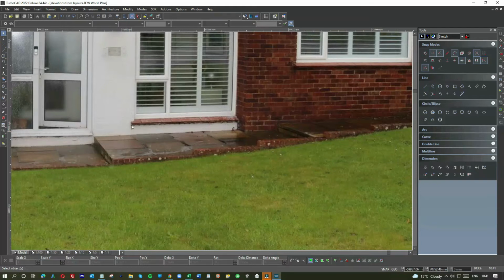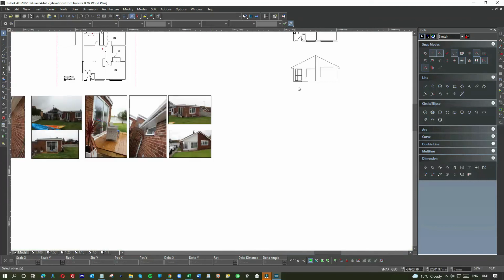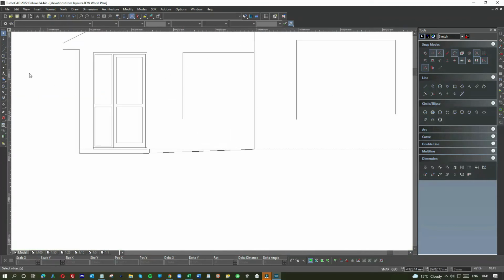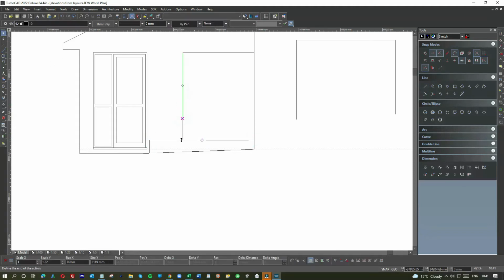From now we'll go 3 bricks up from around this point to create the base for the kitchen, or the base for the window. So to do that, do it from here in fact. I'm going to go 225. And there you go. There's your bottom of the window.